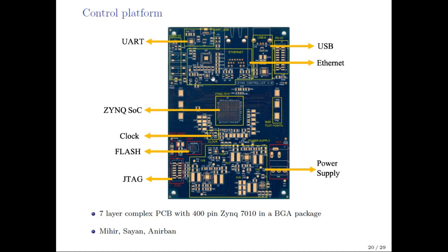To control the hardware, we have used the Zynq SoC from Xilinx, which has dual Cortex ARM processors as well as FPGA fabric. Our concept is like this. We have a launchpad. Basically, this launchpad contains the SoC and some power processing circuits, and also clock and a few communication circuitry to just keep the IC alive. It is kind of a brain structure.